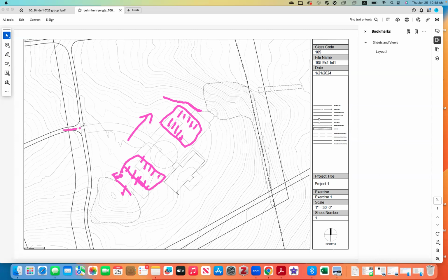Align the center line of this road to your entry road. Start with that. And then the relationship generally works. I'm just not sure if you have enough space. If not, push the whole thing in that direction, so you are 50 feet away from the vegetation, and try to stay away from this steep area if possible. The other thing would be, you do need a more spacious plaza.